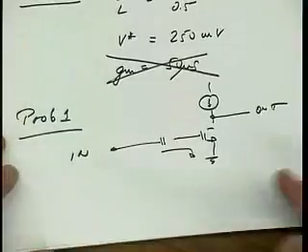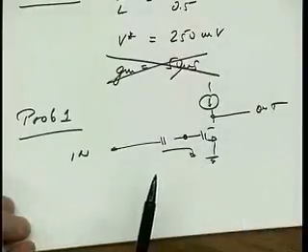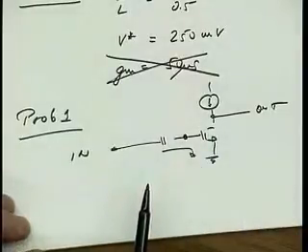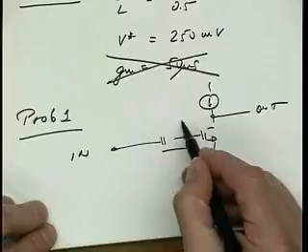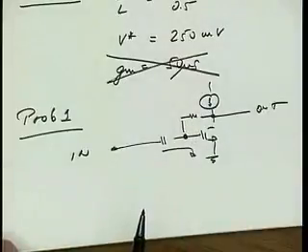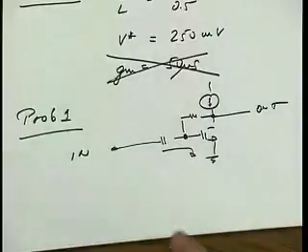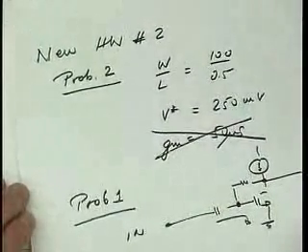Whenever we have such a situation, we of course need to provide a bias for this node. There are a bunch of ways to do that, but one solution is to use a very large resistor. For example, the simplest would be to use a humongous resistor like this. That would provide a little bit of feedback, but not very much, right? Okay. So, other questions?